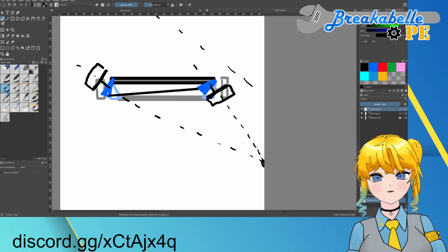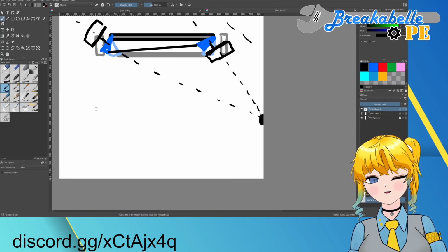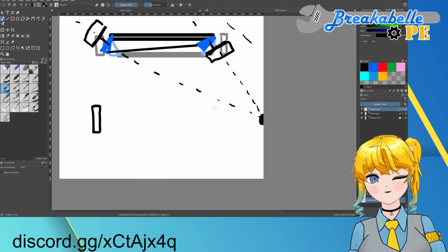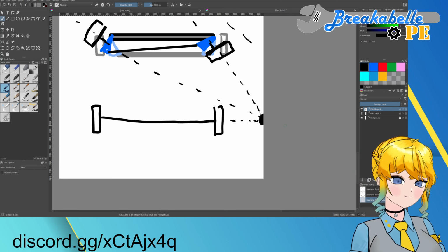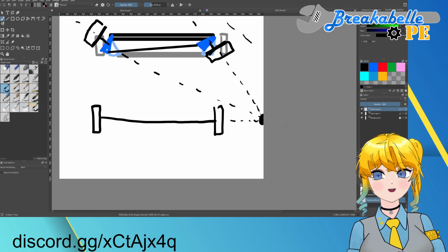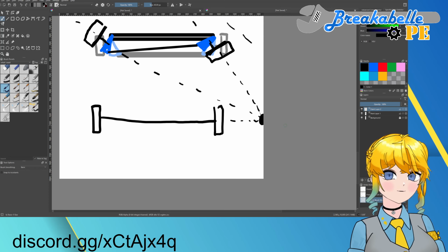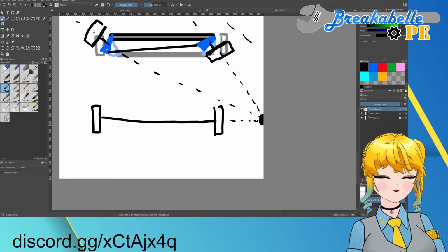So now we do have a point that the car can turn about. All that's left is to make sure that when we design our car with this geometry, that point is in line with the rear tires. And that way, all four tires will always be perpendicular to the one point that the car needs to rotate about, and we can turn the car without slipping.